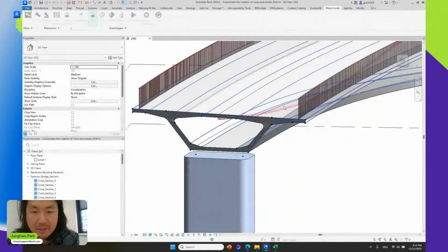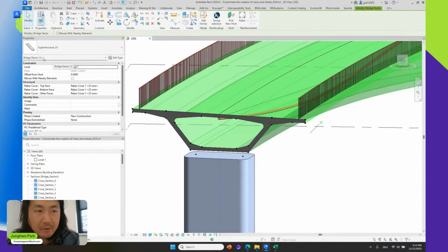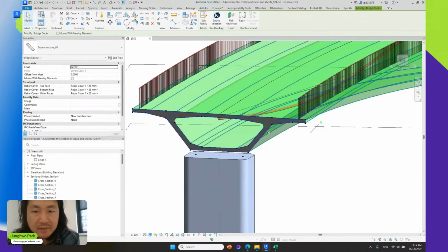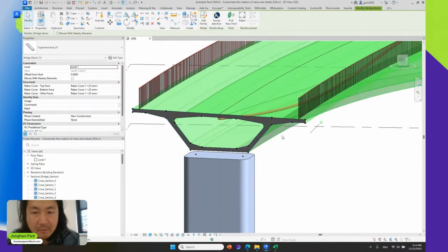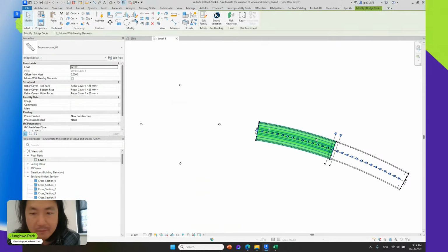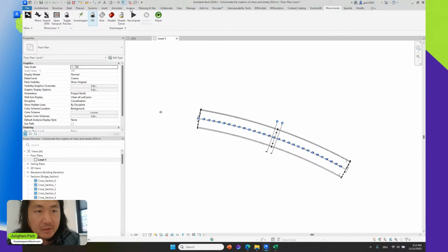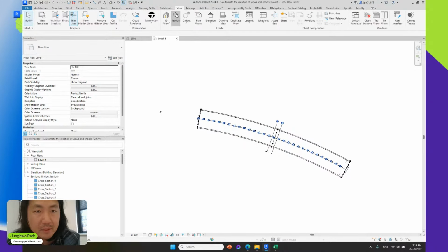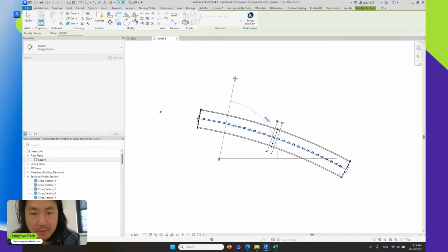these geometrical elements as a native Revit model, and they have the correct category. This is no longer a direct shape, rather this is an actual Revit family, so you can actually edit. So if I go manually to my floor plan, and generate a section here manually, then you should get the native, typical Revit section drawing.